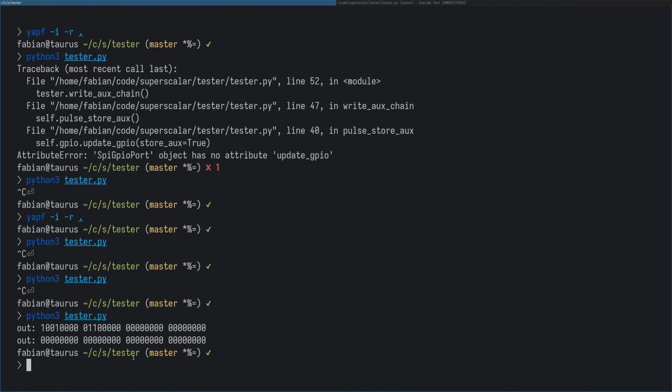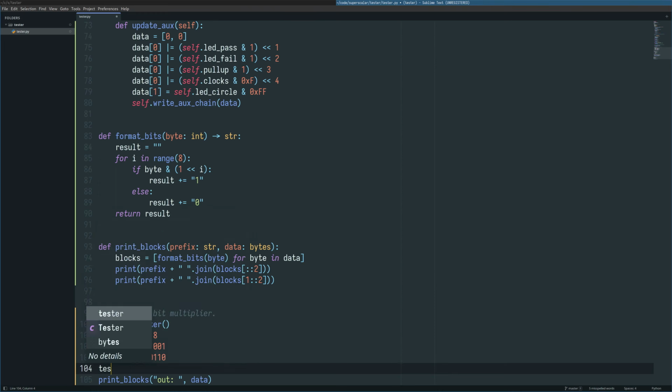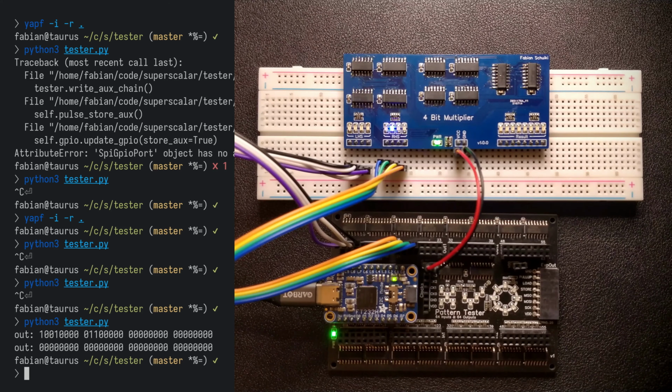It does. This looks pretty good. So the first byte, the one up here, you can see we have set to 1001. This is where the LHS is connected. Byte number 1 we have skipped. Byte number 2 is the one where RHS is connected. And then in the lower 4 bits here, we have a different pattern, 0110. And now all that's left for us to do is to actually write this to the main output chain and see what happens. Let's give this a try.